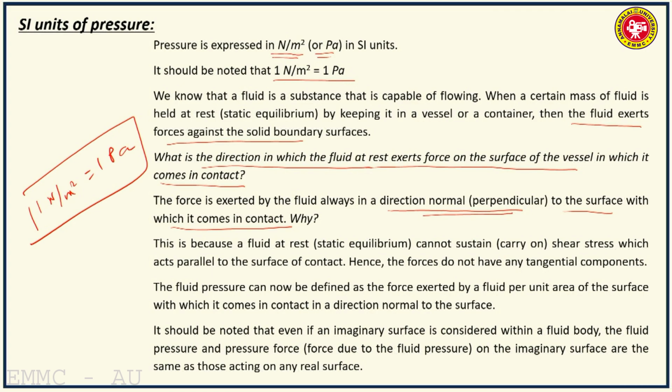So why? See, the force is exerted by the fluid on the surface with which it comes in contact, in a direction normal, perpendicular to it. So why? Because the reason is very simple. The fluid is at rest, that is in static equilibrium. It cannot sustain any shear stress, that we have already seen. The shear stress acts parallel to the surface of contact. So therefore the forces will not have any tangential component.